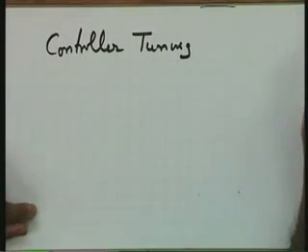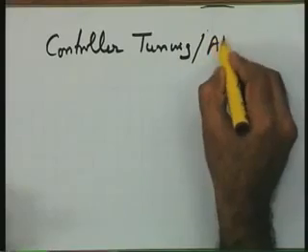This is a method which is extensively used in process control applications, because the information about the process is not available so as to model it accurately. It is a highly nonlinear process model, and therefore, instead of relying on quantitative information about the process, we rely on the experimental knowledge about the process, the operator's experience, install a controller and then tune its parameters, so that an effective tie up between the controlled variable and the command signal is achieved, a process known as controller tuning. And I may say that this is nothing but an ad hoc approach of design.